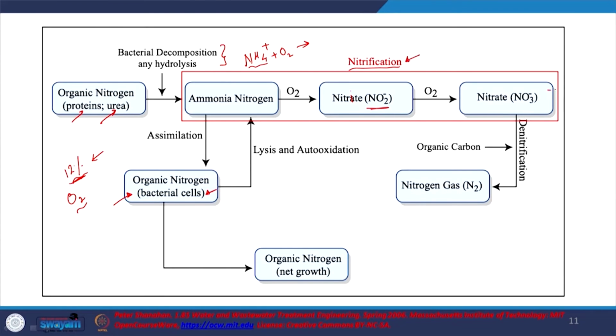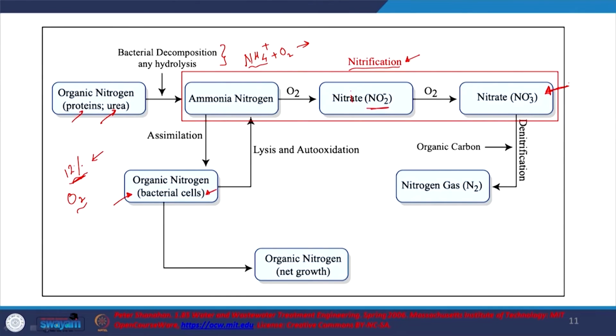But I am still ending up with nitrogen in the water. These are remarkably soluble. I can't remove them by precipitation or by trying to change the phase from wastewater to the gaseous phase. I can't do that, right. So, what do I need to do? I need to transform it into a phase which will allow me to remove nitrogen from the water. So, that phase is not the solid which we would have tried to achieve by precipitation, but by changing it from the aqueous phase, meaning dissolved in the water, to the gaseous phase, right. So, here the nitrate will undergo denitrification into nitrogen gas.